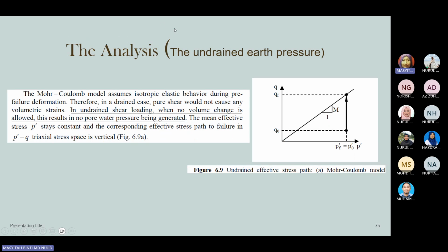Okay, this is again why we explain the Mohr-Coulomb model and also the modified Cam-clay and original Cam-clay. The modified Cam-clay shows you that the critical part of the soil actually reaches the critical state line in a curved shape. However, for the Mohr-Coulomb model, it's assumed that the maximum or failure point meets the critical line vertically, which overpredicts the undrained strength of the soil.